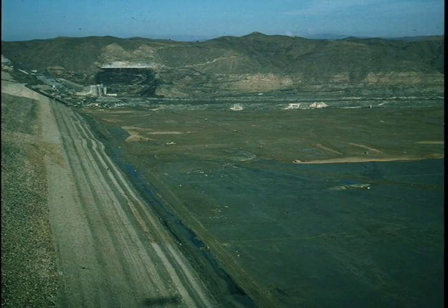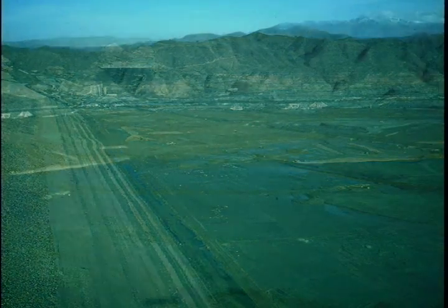Here are 3 photographs which give a panoramic view of the blanket after drawdown of the reservoir. The first view is along the upstream toe of the dam and was taken from the left abutment. The upstream face of the dam is evident on the left-hand side of the picture. In the far distance are the intake structures for the 4 tunnels through the right abutment. The rectangular black area is the cut face of an excavation made on the right abutment for the approach channel to the tunnel intakes. The cut is black because it was made in carbonaceous schist.